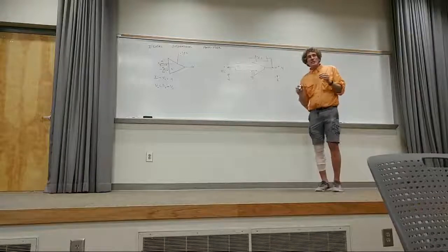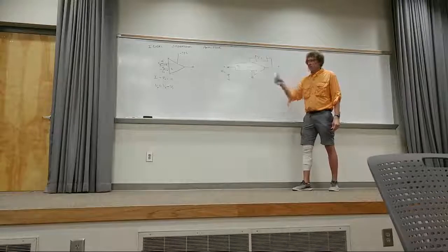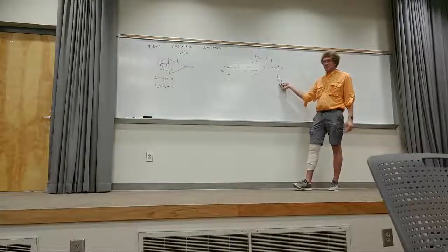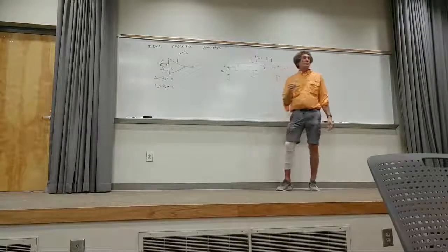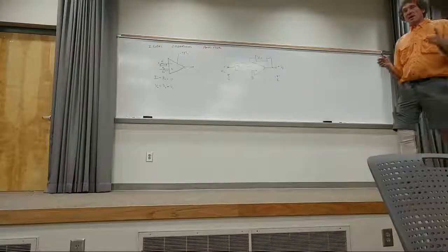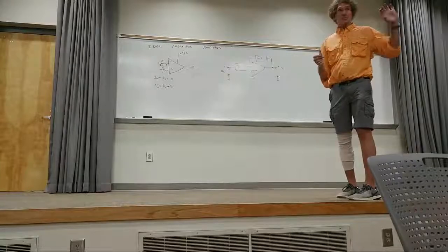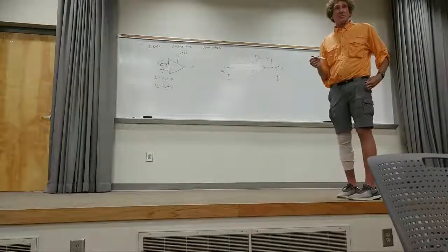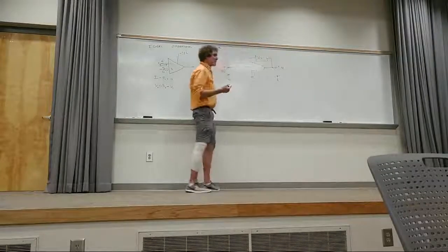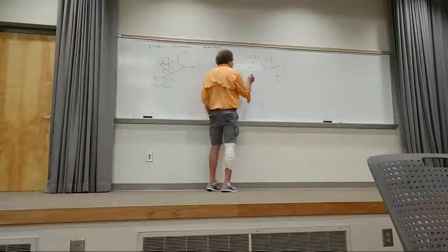Now, usually in the book, they will never show the ground terminals, here and here. They'll show this ground, but everything else is not shown. They assume V0 plus here would be measured with respect to ground. They assume Vn would be measured with respect to ground. That's an assumption. Now, we're going to apply the laws I just told. I said there's no voltage difference across those terminals and no current into the terminals, right? So watch this. When I talk about a voltage with a ground potential, what do you assign that voltage? 0 volts. So there's 0 volts here, right?